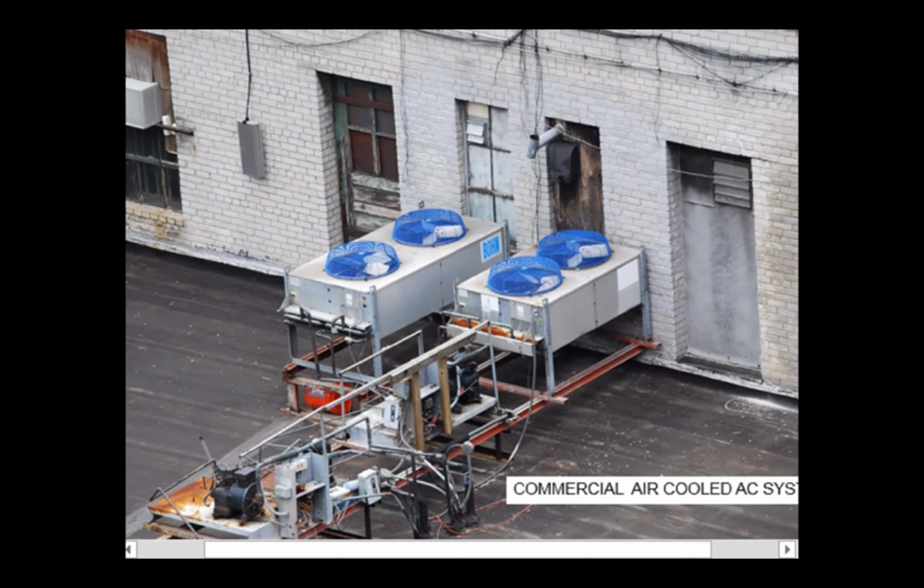And when we find out what we need in our building, we can then find out, from the cut sheet from the manufacturer, what this unit is, how much electrical load it occupies, and how much we need to run service up to the roof to be able to run it. As you saw, we can tie that into our electrical lecture in terms of trying to figure out how many circuit breaker panels, what voltage we're running up to it, and be able to size all that.